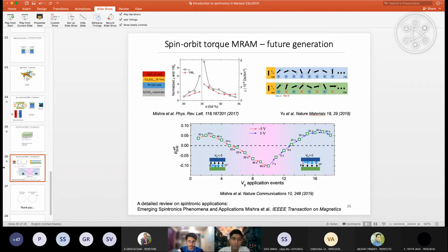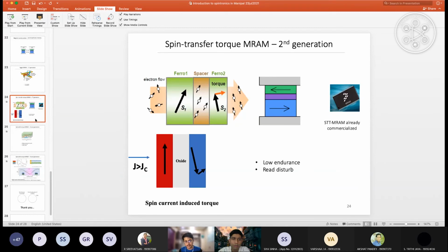Ang asks, what is the Spintronics equivalent of a clock signal to differentiate between multiple bits? A spintronic equivalent of a clock signal. You mean a pulse going up and down? A spintronic equivalent will be your MTJ, which is switching from one state to another. That's what I can say. Resistance switching up and down. So your magnet you are switching in two different directions. That can be a spintronic equivalent, I can say.